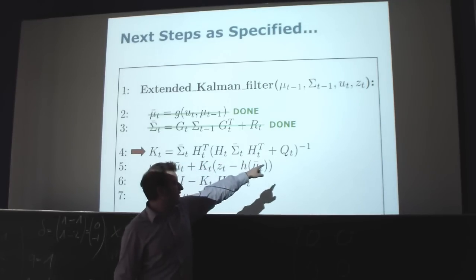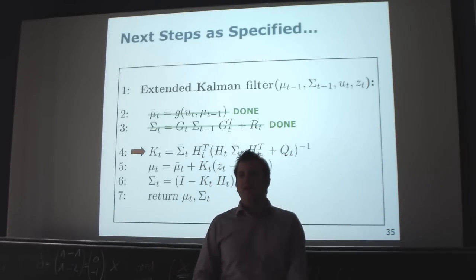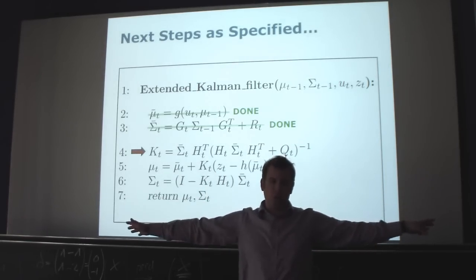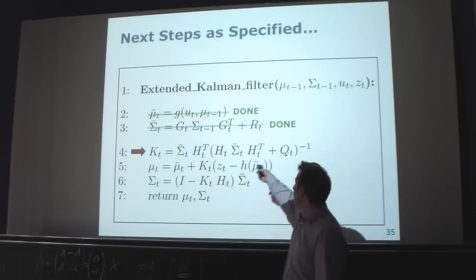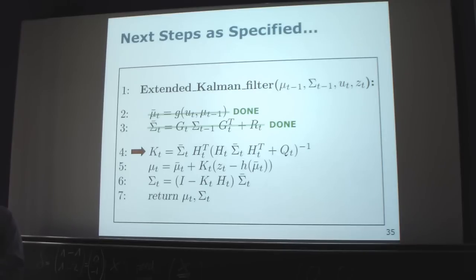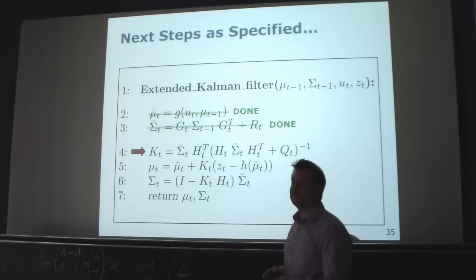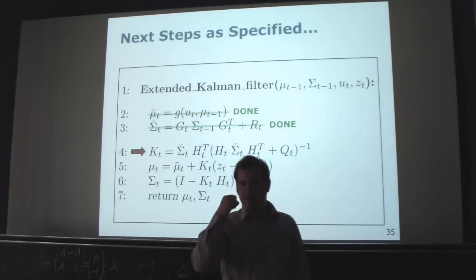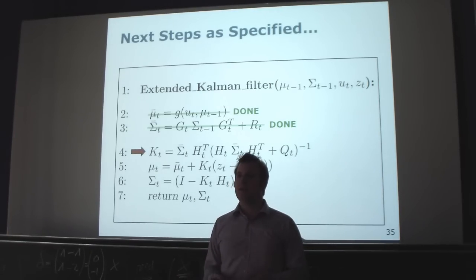It's not that the dimension of this matrix can grow and grow and grow, so that the inversion becomes a super costly operation. This is not the case as soon as we move to reasonably sized environments and have regular sensors. If you have a sensor which always observes the whole world, this is a super costly operation, but this is not the case in reality. So although this can introduce a cubic or near cubic complexity, this is only affected by the dimensionality of your measurements, and so it doesn't dominate the Kalman filter. What practically dominates the Kalman filter in the SLAM context is this quadratic matrix where all elements get updated. There are n squared elements in this matrix which get updated, and this leads to a quadratic complexity in the number of features we have.